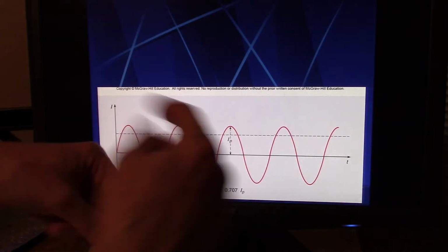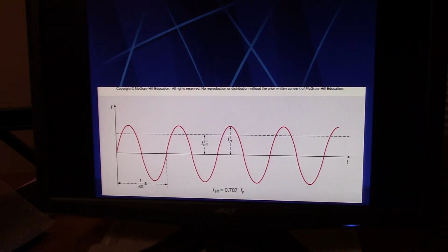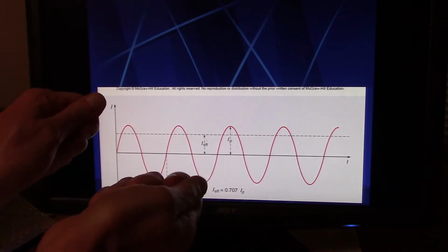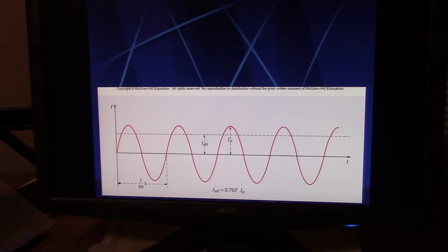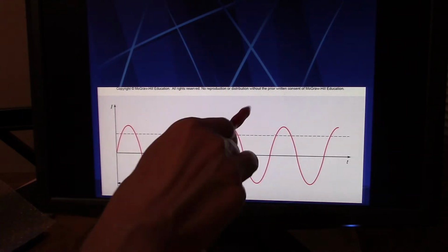Physically, the windings in that motor are spaced for that. If you take those motors to Europe, they're going to get hot. They may not even work because there they use 50 hertz, so it's not going to be efficient. You have to buy different devices there. So this is the way things work in America, okay?